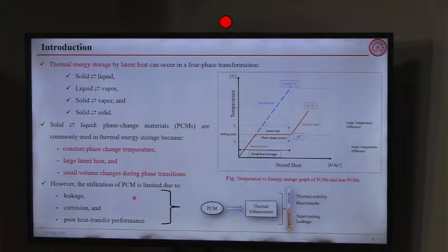So if you want to know how much a 2 kg of water at 50 degrees centigrade will store energy, you multiply it by that 4 times 50. That will give you the total amount of energy which that 2 kg of water stores, and liter for water or kg does not matter.